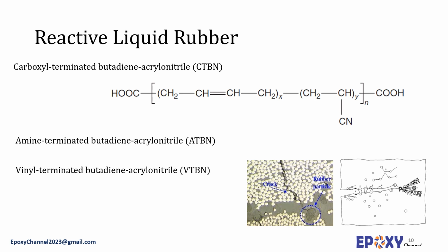ATBN liquid polymers usually are not mixed directly into the epoxy resin component, since cross-linking and shortened shelf life will result. ATBN adducts are often mixed with the curing agent component of two-component epoxy adhesives. ATBN tougheners also increase the ultimate tensile shear and T-peel strength and environmental durability using conventional room temperature curing agents such as fatty polyamides, amidoamines, and amine ethers.